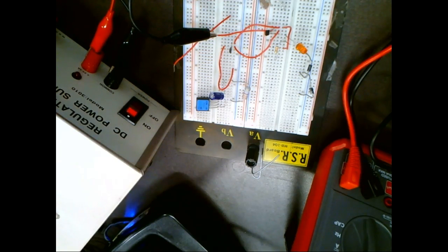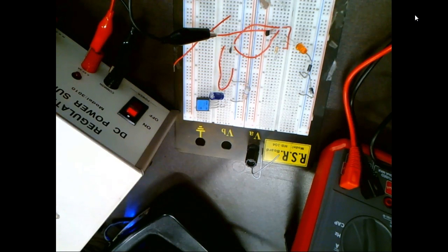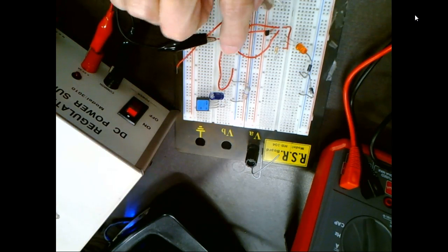Why do they need 3 leads? 2 of them going to be power. And then one of them's going to be the signal. These are DC. So depending on how you power them up, we'll look a little bit at the data sheet. I think they can operate from 5 volts up to 20 or 30 volts. Most of the time in PLCs, when we use DC, we deal with 24 volts. So that means if it detects the magnetic field, it would give you 24 volts. If it didn't detect it, it would get what? 0. Or vice versa. This guy right here is a little different. I have to figure that out. But that's a Hall effect right there.